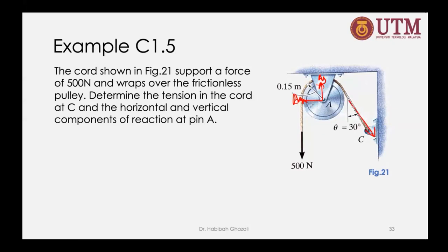But we know that according to Newton's third law, if an object A exerts a magnitude of force on object B, object B exerts the same force on object A as well. So here, the distributed load will cancel out. You can assume that it's internal forces, so it will cancel out. It's not going to be included in your calculation.